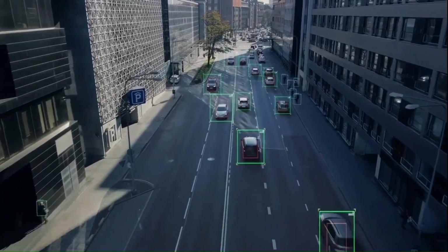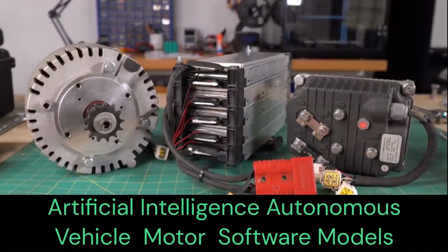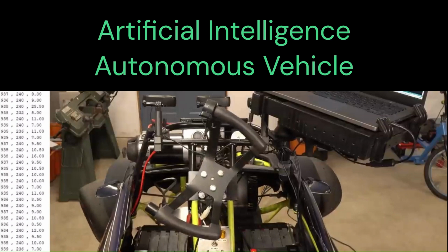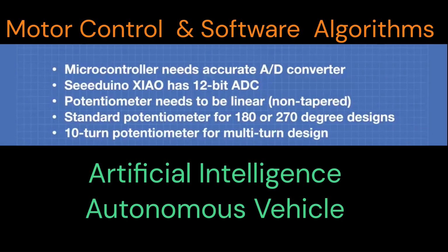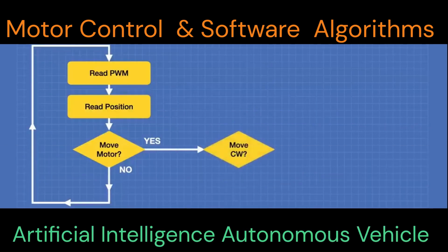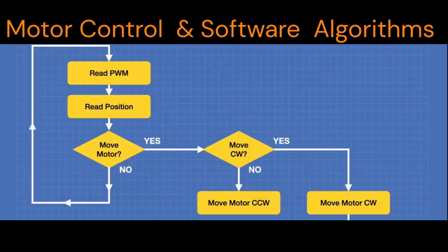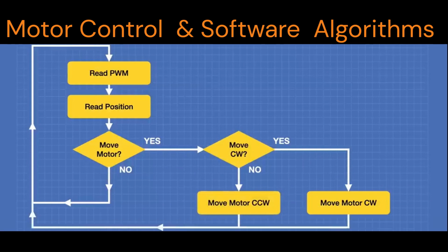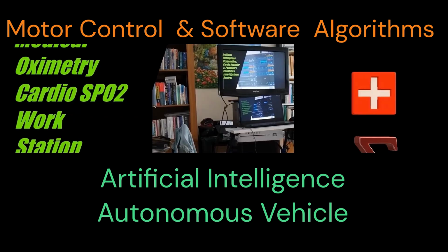The DC motors are connected to the driver board. The drivers are installed in a mirror configuration, so it is required to reverse the polarity of the power supply to one of the motors, because the motors are DC. The change of polarity will reverse the direction of rotation of the motor shaft and will synchronize the direction of the rotation of both motors.